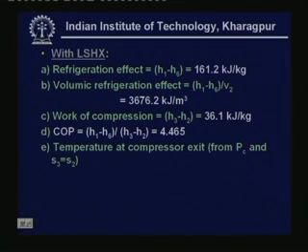Then the temperature at compressor exit, we find this from the pressure and the entropy values. You find that it is almost 105 degree centigrade, it is 104.9 degree centigrade. Okay. So, this is the performance with the liquid suction heat exchanger. Now, let us find out the performance without the liquid suction heat exchanger. Again, what we do is we apply the energy balance across evaporator, compressor, condenser, etc., and then find out the required parameters. Okay.